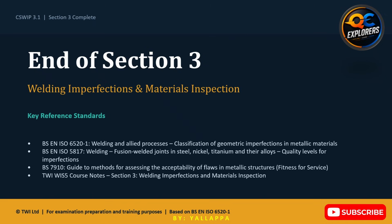For your examination preparation, there are 4 activities I strongly recommend. First, revise the 15 key examination points from the previous slide. Second, study the applicable acceptance levels of BS EN ISO 5817 and understand that the actual project specification determines which acceptance requirements apply. Third, practice identifying imperfections from radiographic images. And fourth, repeatedly review the 4 factors associated with hydrogen-induced cracking and the corresponding prevention strategies.